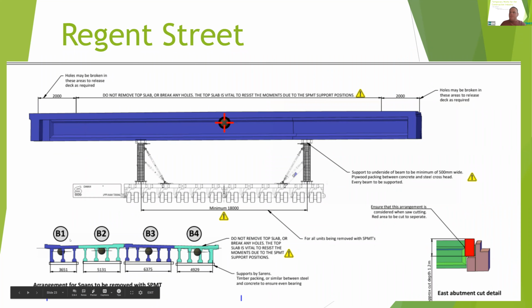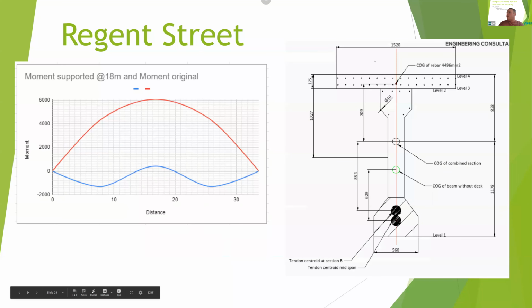So that means when those beams were sitting, spanning from pier to pier, they had to support the dead weight of the wet concrete. Now that's important because that means that with just the dead load on this structure, this top slab is not in bending, i.e. it's only spanning from beam to beam. It's not involved in carrying the moment due to the dead load of the structure.